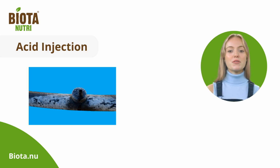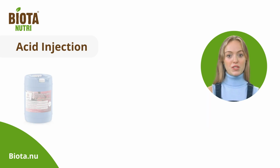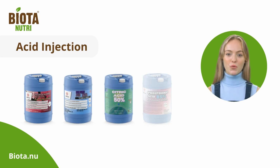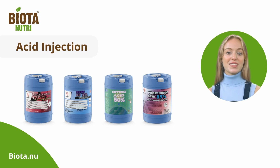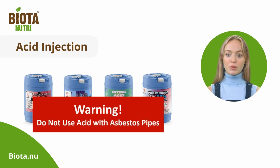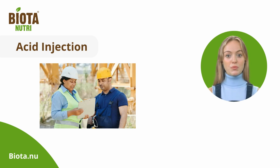These impurities can often be dissolved by lowering the pH of the water, usually by injecting dilute solutions of acid, such as hydrochloric, sulfuric, citric, or phosphoric acid. Phosphoric acid has the added benefit of adding phosphorus to the soil. Please note that acid should not be used if asbestos cement pipes are part of the irrigation system, as it will attack the pipe wall and release fibers, leading to mass blockages. Acid and chlorine injection requires skill and the following of safety procedures. You may want to hire a contractor to undertake these types of maintenance at your facility.